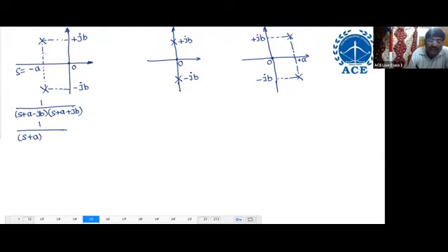How many poles are there? 2 poles at minus A, one positive imaginary, one negative imaginary. 2 poles, so put it square. Plus the product of the imaginary: plus JB into minus JB is B square. Or simply write like this: S plus A minus JB, S plus A plus JB, so A square plus B square. S plus A whole square plus B square.